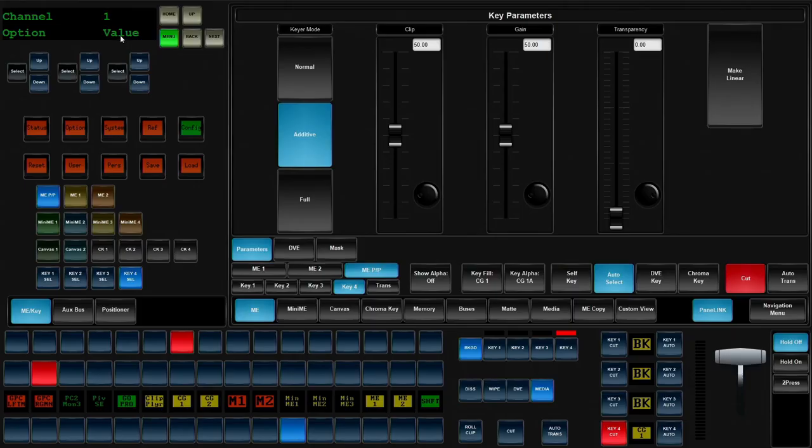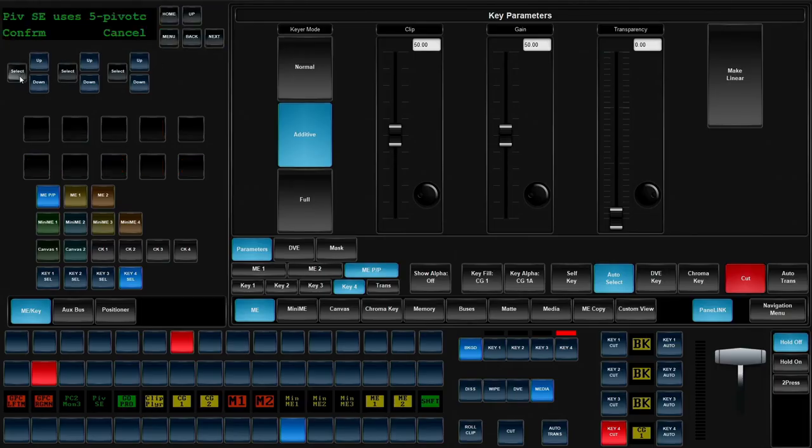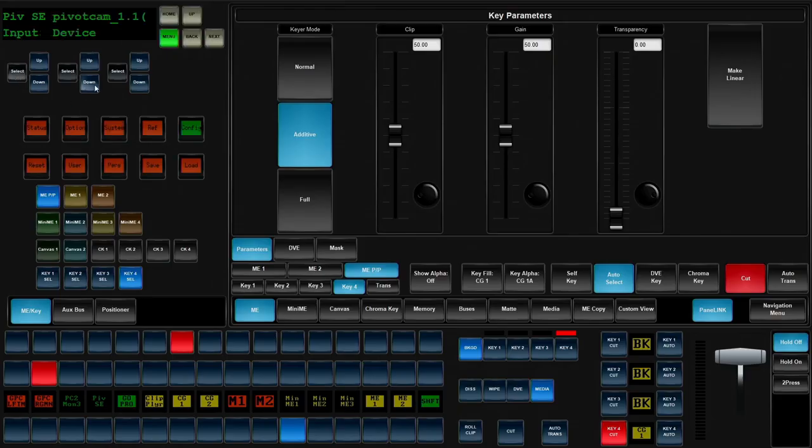This will be channel 1 because it's camera 1, but also because each pivot I would be creating would be a separate instance and assigned its own individual port. So for camera 2, I would have gone 2568. Invert pan is in reference to how you're feeling the switcher control from the knob. It's up to you. Same thing with tilt. These are the parameters you're more comfortable with. Click select and confirm that assignment.